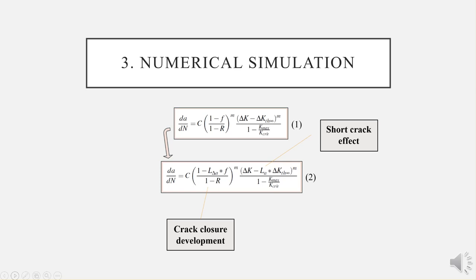In order to calculate the propagation life, one needs to compute the stress intensity factor. This was done making use of a weighting function methodology. It must be pointed out that the crack is defined as the summation of both the actual cracked region surrounding the initial defect plus this initial defect itself. So the defect is part of the crack.